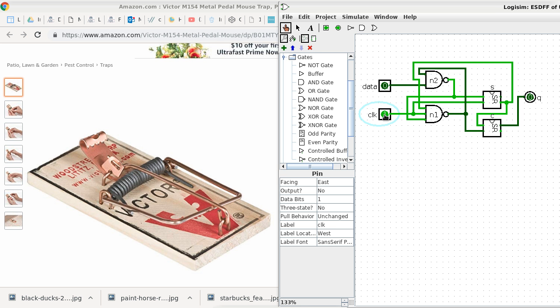It's good? Yep. What's the use of the data pin? Well, the data pin still dictates how you want to change the output. So if I want the output to become a 1, I got two things to do now. First, I have to change the data pin to a 1, and then the second thing is to create a rising edge, which means the clock has to first reset back to 0, and now go to 1. Then the output is now mirrored. Yep. So the data pin is still, if you look at this as a copier, okay?